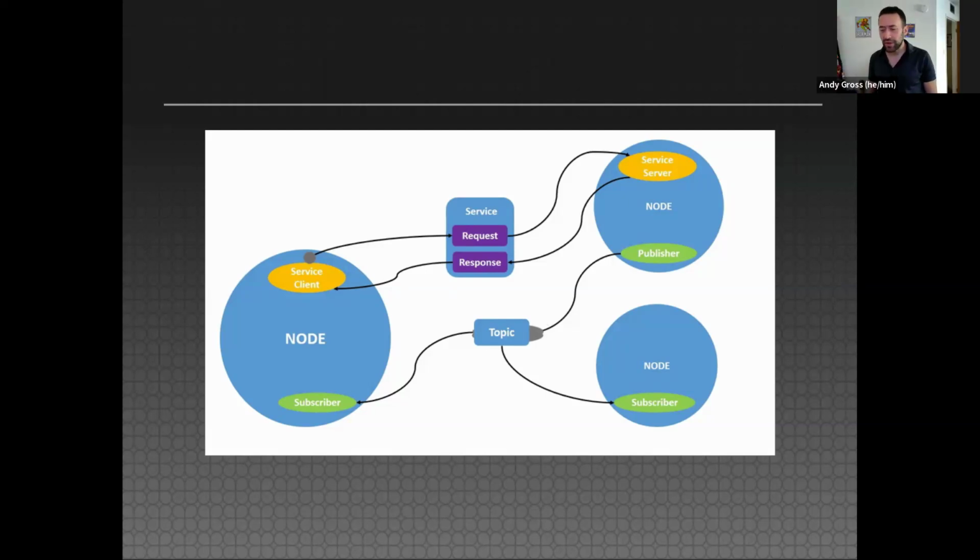That is a great question. The answer is it's closer to a thread running on a computer, but it's extremely flexible. And this is what we did when we were building this robot: the Roomba has a lot of onboard processing. That is doing its thing, and then it is sending information over serial, and the serial connection is essentially forming its own node, and then ROS is interpreting that serial information, translating it into the appropriate formats and publishing it as topics for the rest of the system.